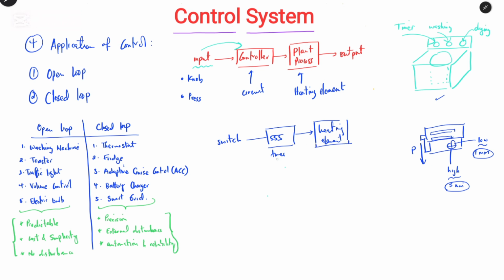So once the timing is done, if we select, for example, low, then after 1 minute this push button will be released. Now it will be in the upward direction and the heating will be stopped, because we don't really need the accuracy, and also we are not concerned about the reliability of how this toaster will operate. It won't care how the bread will be prepared afterwards, whether the bread will be toasted to an extreme or only a limited degree. This particular toaster does not care.